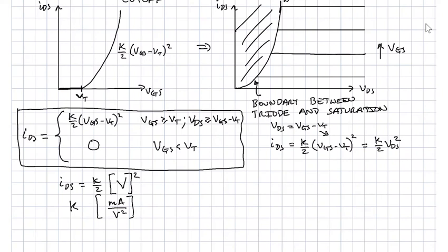And how do we get to those units? A lot of times we'll break up this K, and I'll try to be very clear when we're going to use an overall K or break it up as follows. We will call it Kn, n for NMOS, with a prime, and then pull out two dimensions of the MOSFET itself, which we drew in the last lecture, W over L. Because sometimes we have a PMOS or an NMOS, we may choose to subscript these with an n because we're in the world of NMOS here.